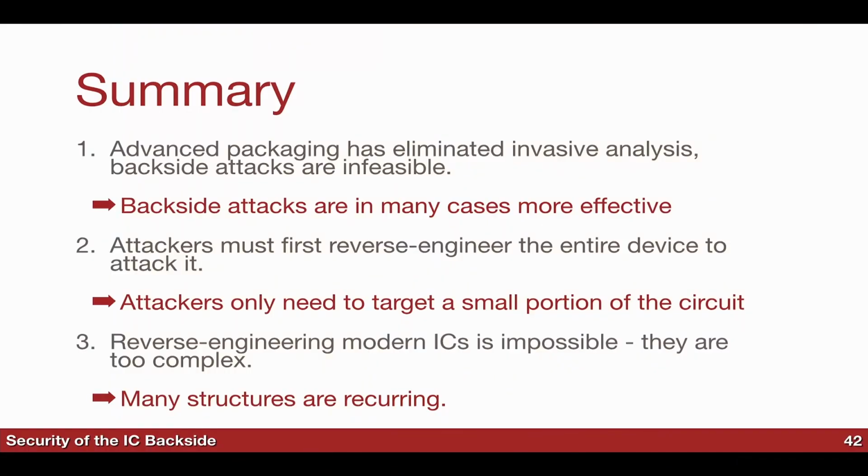But anyway, the kind of summary is, a lot of these are claims that we hear a lot, especially if you send in academic papers and reviewers send them back to you. Like, we have advanced packaging, invasive analysis is never going to happen. And the truth is, like I showed you, we don't even need chemicals anymore to open up these chips. Now you have a backside polishing machine, you put your chip in there, you let it polish away, and you get a very nice result. After that, you only need a FIB. You don't need all of these disgusting chemicals that nowadays are very hard to get at universities, who don't want to get sued by health insurance companies.